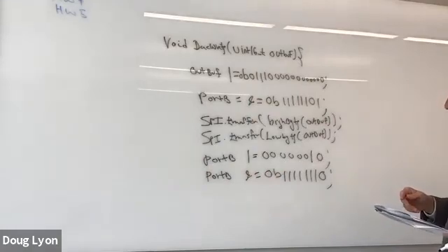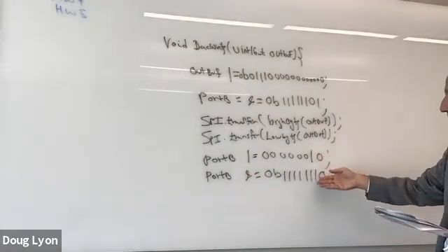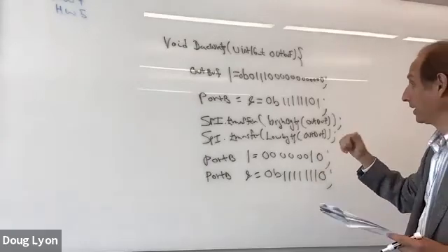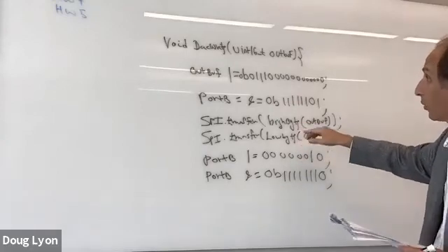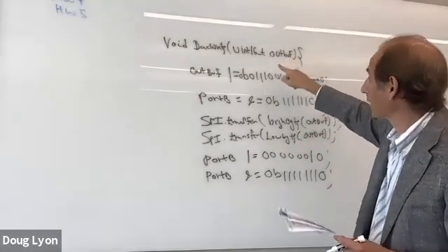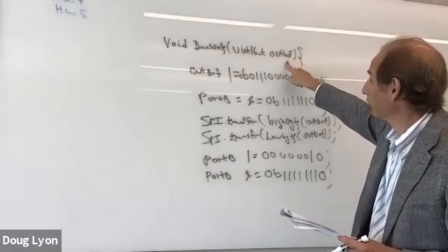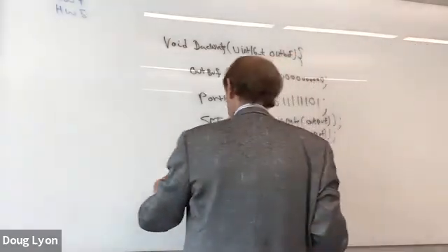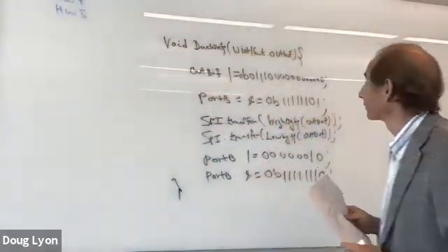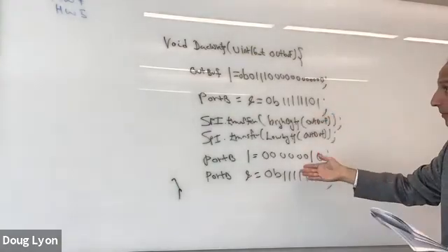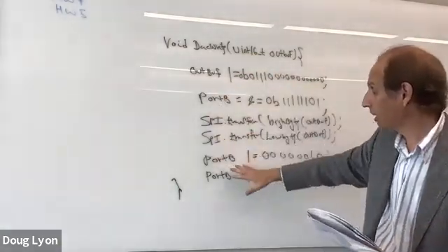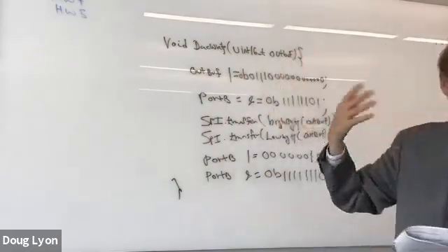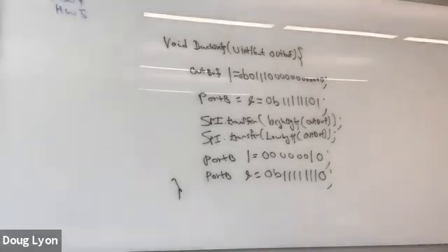And what that does for me is it allows me to communicate one bit at a time out to the MCP 4921 and chug out my sample. And all I have to do is call up DAC write with a number that ranges from 0 to 4095. And now I'm able to write directly to the DAC. And I can write whatever I want. And this will handle everything for me because I've contained the complexity of the bit flipping inside of the DAC write command. So I can just keep calling DAC write and write out samples.